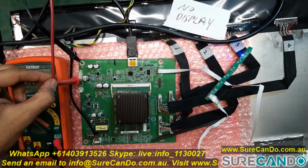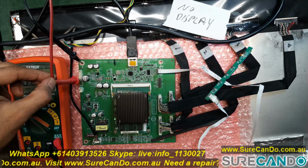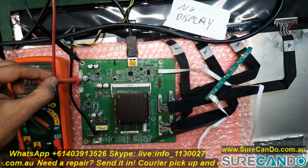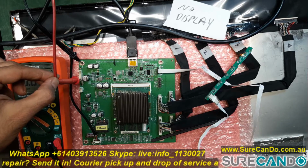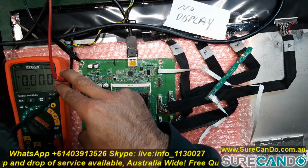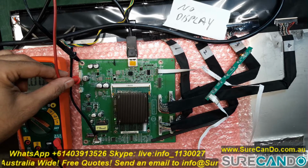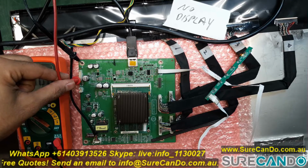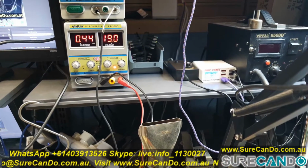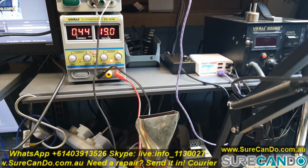Then I wanted to see if there was maybe a short, maybe my power supply can tell me. So I manually powered it up this way, giving it the 19 volts it needed, and had a look at the power supply. It was drawing amps accordingly. When the backlight was on, it was pulling just above 1 amp, and when the backlight went off, it reduced to 0.4 amp. So you can see 0.4, and the behavior is all good, and the shorting light didn't come up. So I assume there is no problem with the power supply or the controller or any of the components.